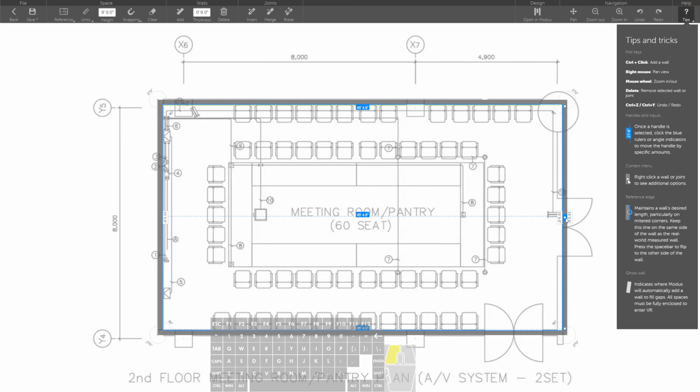You'll notice I didn't put any of my doors or columns, or if I had inside walls that were in the room. Those don't get added at this time. You're only tracing the outside walls here. And it doesn't have to be a rectangle. It could be whatever shape. You would just follow your floor plan that you've imported.